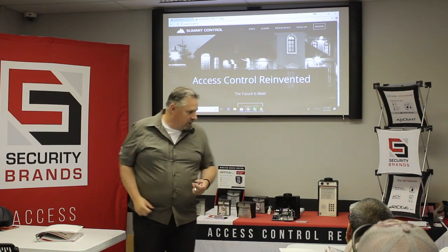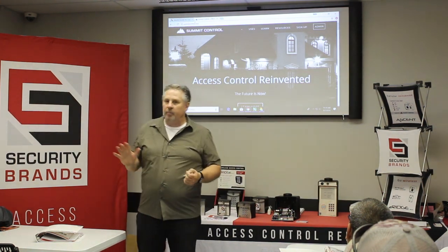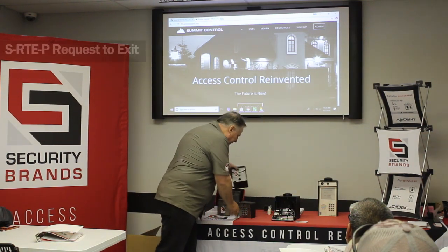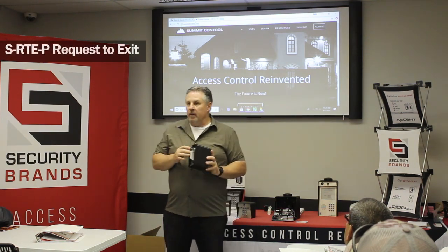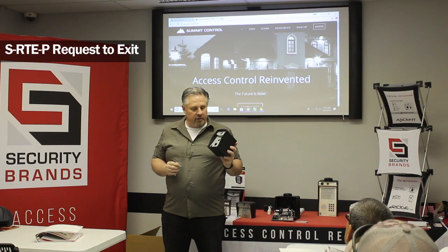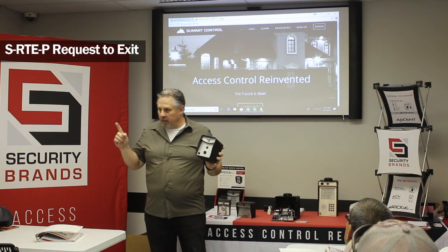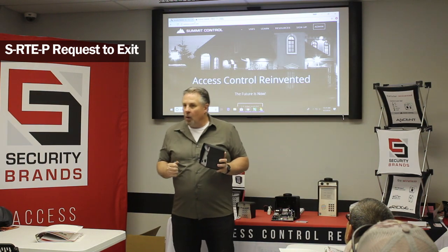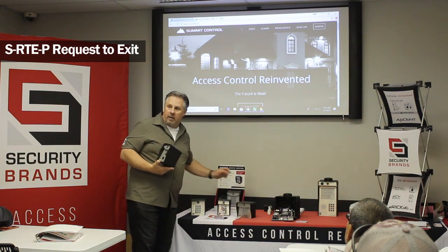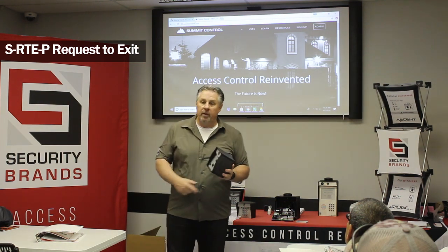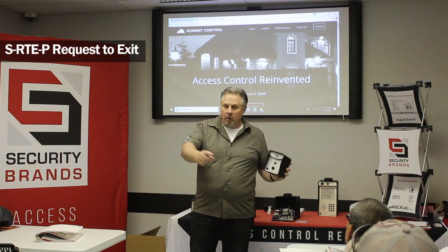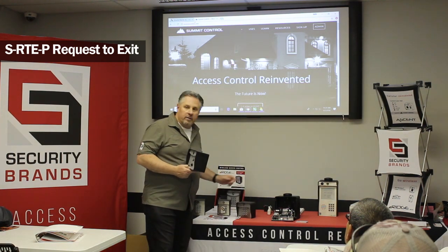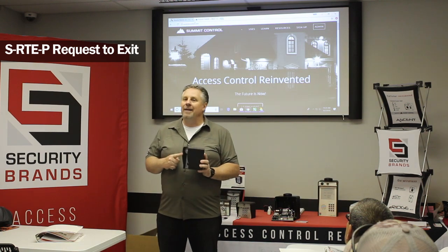So that's card readers. I also have fire access and pedestals, and request to exit. In fact, I've got my request to exit here. I like to use the example of a pool. You have maybe a card to get in at the pool, or you can use my wireless keypad to get in. That's really a nice way of doing it, because usually all the concrete's there, and you've got shrubs and ornamental iron, and you don't want to dig anything up. So you put in the wireless keypad, and then you have a request to exit to get out.